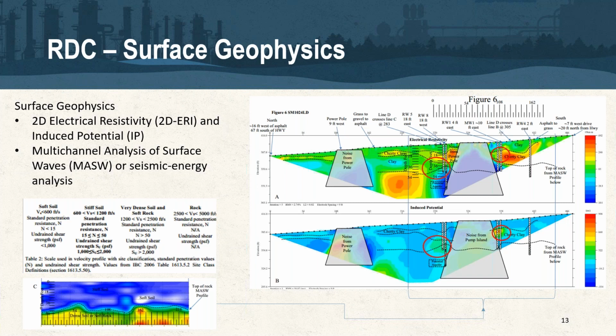And then the bottom left there, this is a seismic profile, multi-channel surface wave analysis of the same site. And you can see how combining these different geophysical tools will allow us to look at areas where we may want to target denser rock, or if we're doing a transition zone where we need to know that softer or weathered unit is that we need to drill into to actually treat this contaminant's concern in that interval.